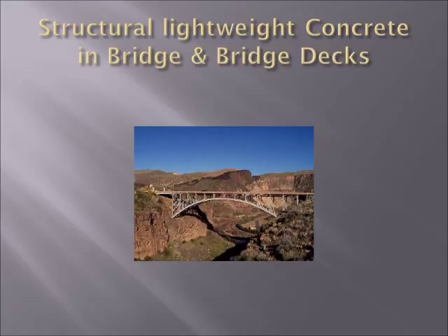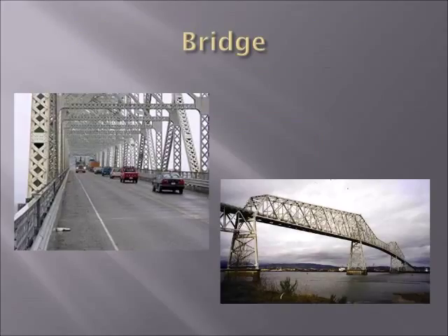Historic bridge retrofit is an area of common use for structural lightweight concrete. If you have a historic bridge that needs to be updated to handle today's traffic volumes and traffic loads, structural lightweight concrete is the preferred method to be able to go in, replace that deck, and keep the historic structure.